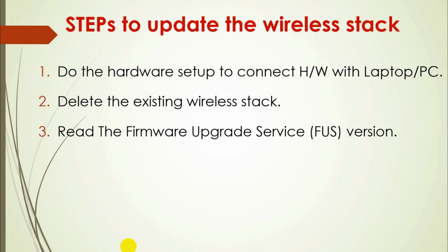The version of the FUS will be the initial version developed by ST. Then you need to update the FUS to the latest version given by ST. The purpose of the FUS is that once you update the firmware, it first authenticates that your firmware or wireless stack is actually delivered by ST itself.